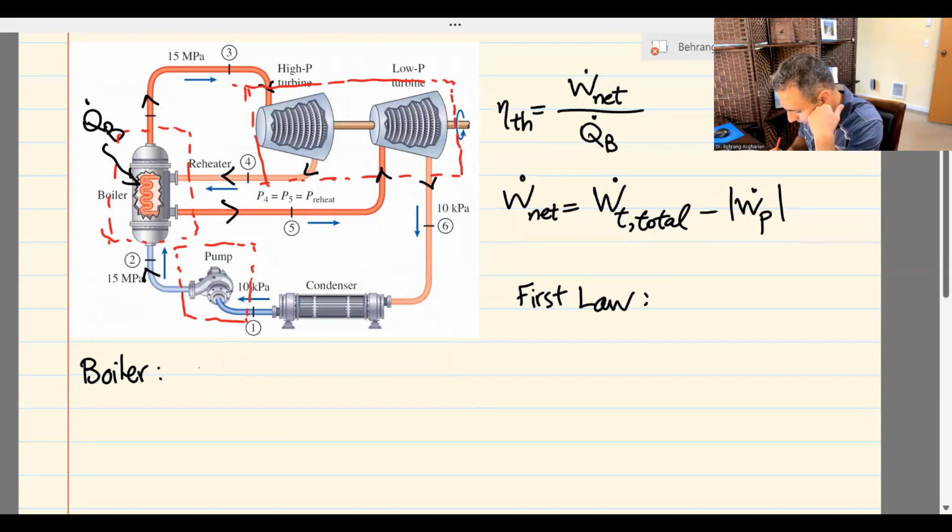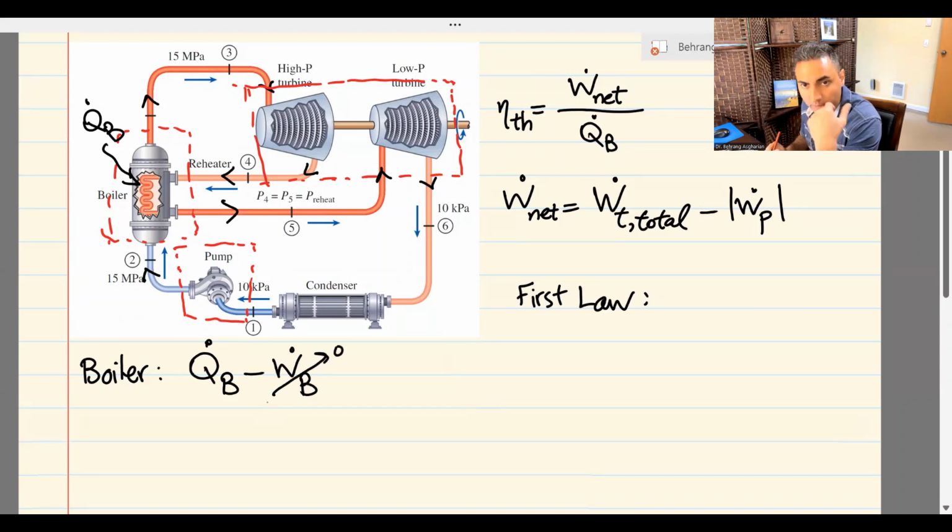So I apply the total amount of Q dot for the boiler, and there is no W dot, so W dot net for the boiler is obviously 0. And all these streams have the same M dot, luckily for us, so I can factor out M dot. In some cases, like a regenerative Rankine cycle, these streams are not the same M dot. There are some mass fractions that you need to take care of. But for this case, all of them are M dot.